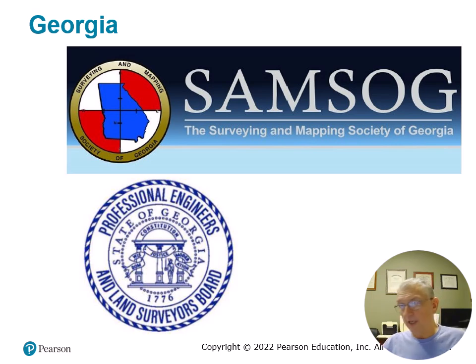Technology is really awesome. We have geo-referenced aerial images that are available from paid services. What you see on Google Earth is wonderful, but it might be off a few feet, and it's hard to get it geo-referenced. We use some subscription services that will put them to 6 inches or sometimes less of pixel resolution and on state plane coordinates, like a GIS system would.